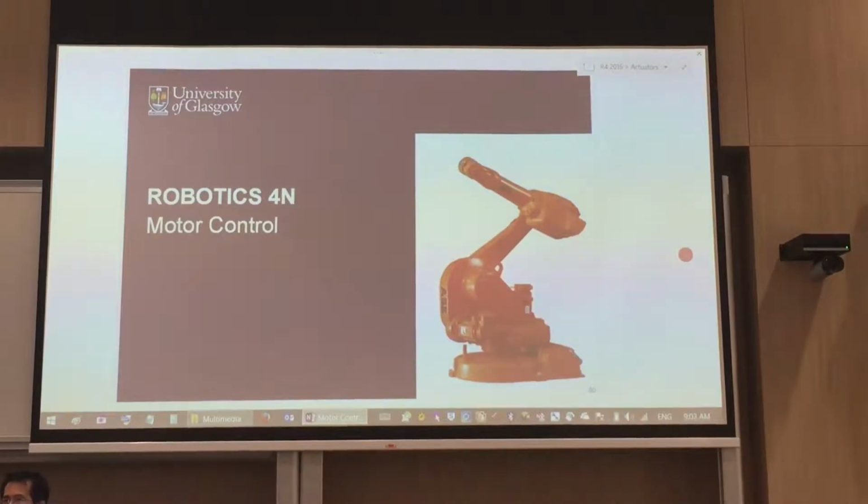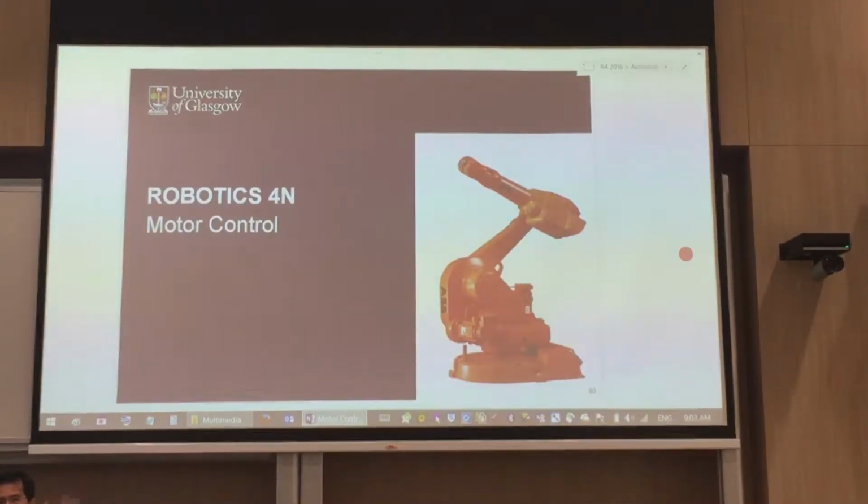The H-bridge, which we will be seeing, we use to rotate the motor clockwise or anti-clockwise. You can see the control block diagrams and transfer functions of the motors, particularly looking at two cases. One is that the motor is driving a load directly without a gear, and then we look at the output load position relative to the rotation. The other transfer function that you get to see will be a motor system with a reduction gear.